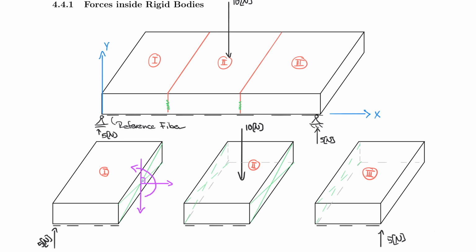But now, in a two-dimensional sense, if you look at this picture without these diagonal lines, these three entities, the shear force, the normal force, and the bending moment, are capable to keep this glue and the system in equilibrium. Of course, in this case, the normal force here is 0, right? Because there's no external force acting here. But we still need the glue to be able to transfer that. All right, now we have one system in equilibrium.